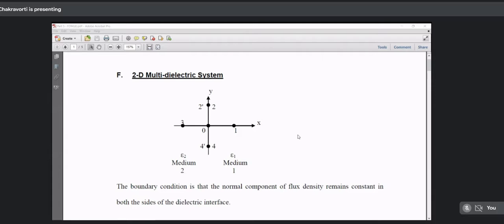First, remember our basic assumption is that the field distribution is linear between two nodes, two connected nodes. Now, if two dielectric materials are present between the two nodes, then this linearity is not possible, because at the boundary there is a discontinuity. So what can be done?